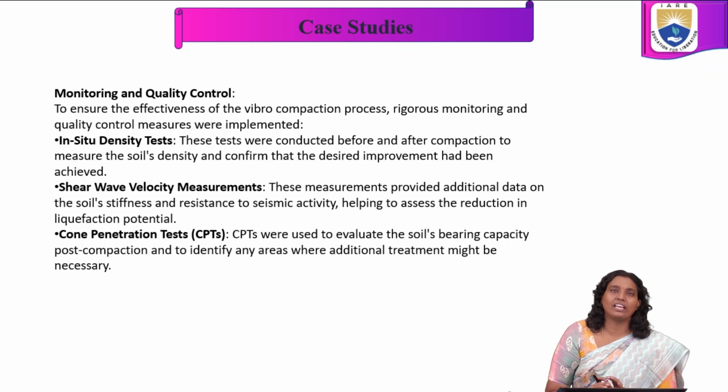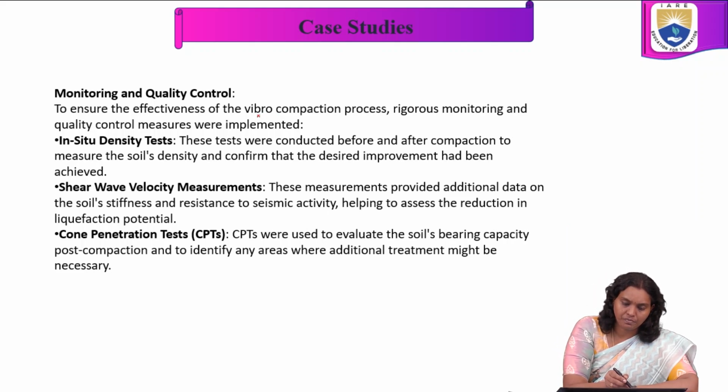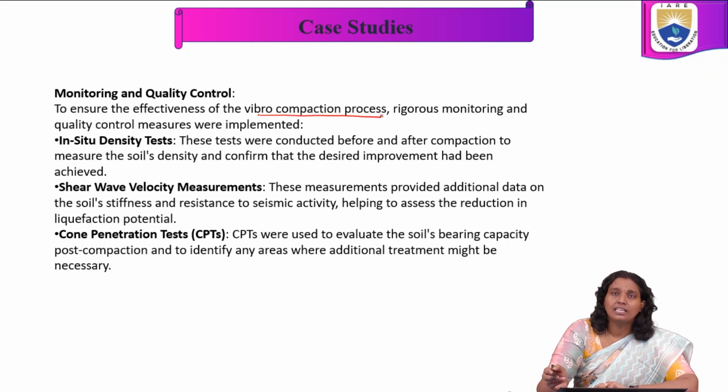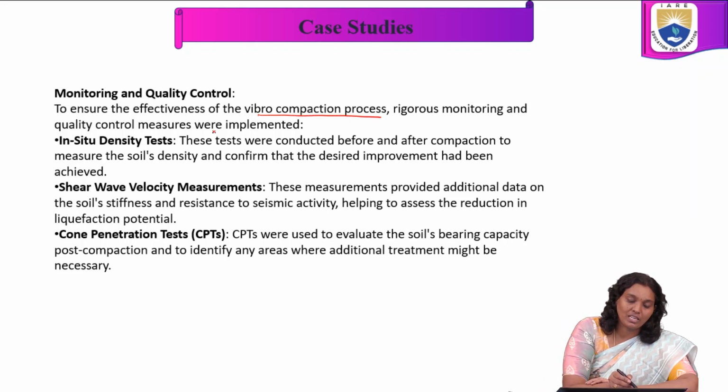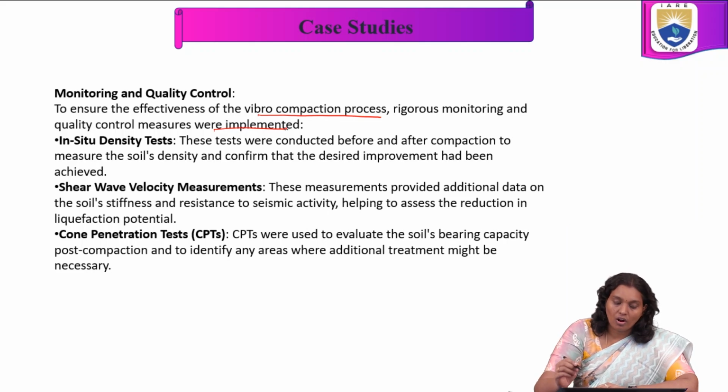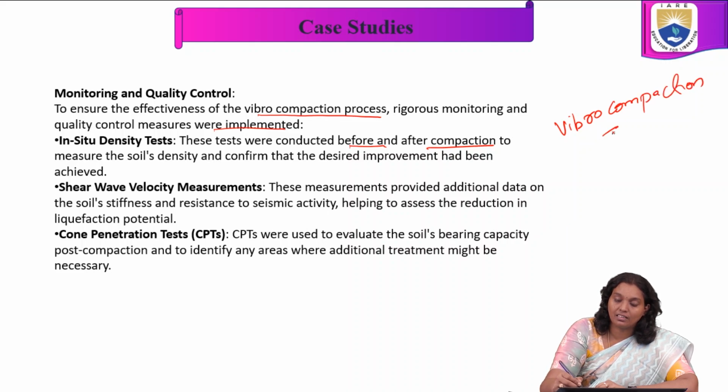Now, how we do monitoring and quality control. To assure the effectiveness of the vibro compaction process, rigorous monitoring and quality control measures were implemented. On-site in situ density tests were conducted before and after the vibro compaction process. Before and after, we are conducting these tests.